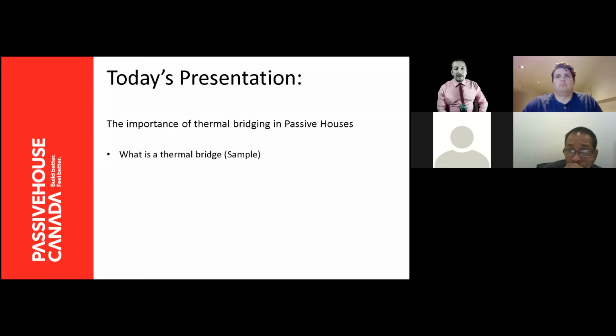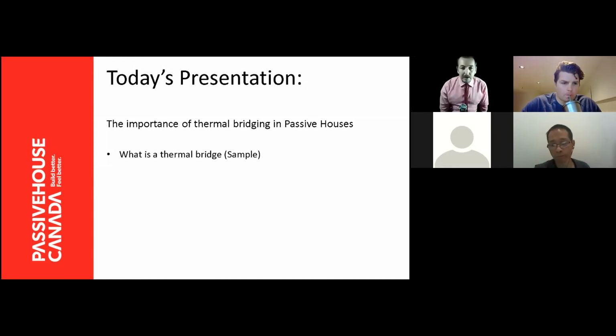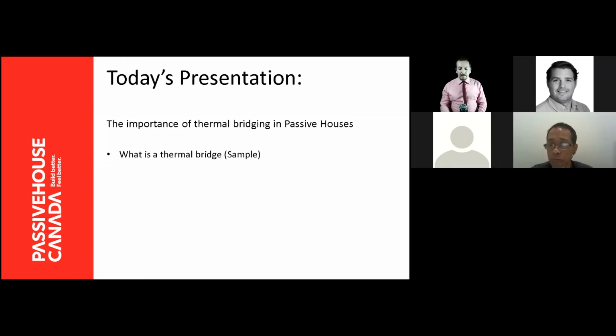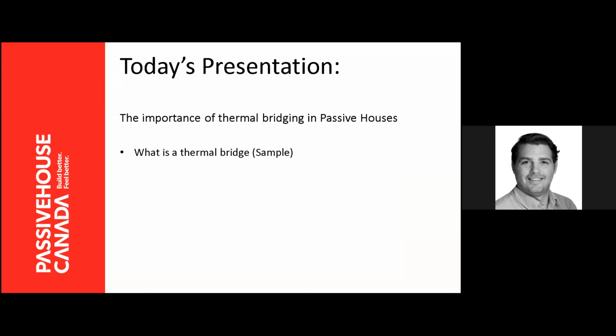So I remember when I first went to my first thermal bridge training course, coming out of the course, I was boggled. I was completely disorientated. It was hard going, and the one thing that I took out of it was that all you are doing in a thermal bridge calculation is correcting the curved heat flow at a junction in the building. And I'm literally going to explain it to you that simply. That's all it is. We're just making corrections for each of the different places where you've got inhomogeneous heat flow.